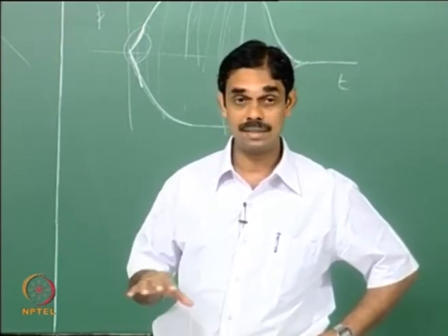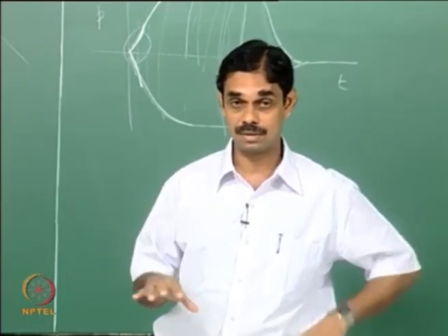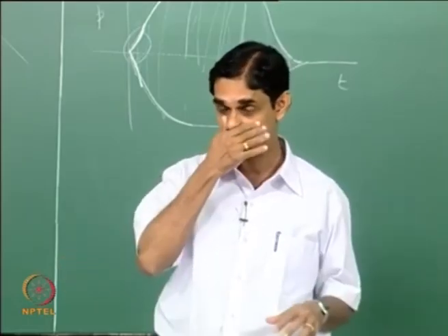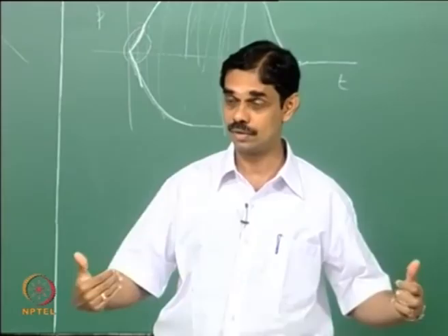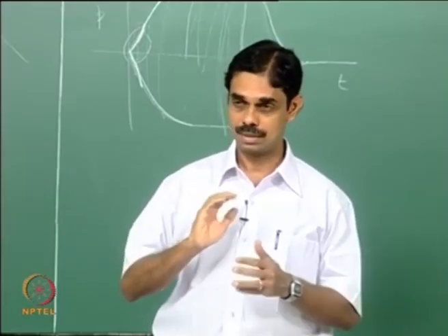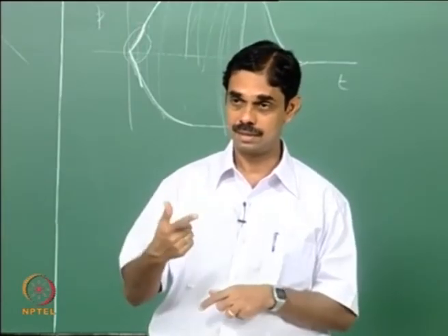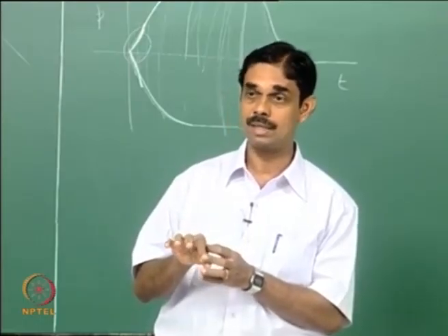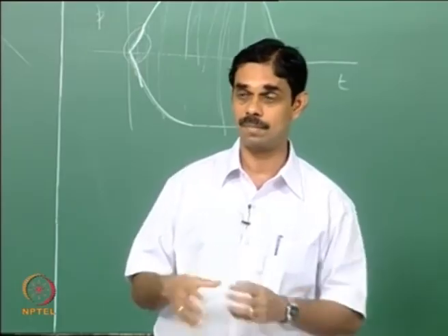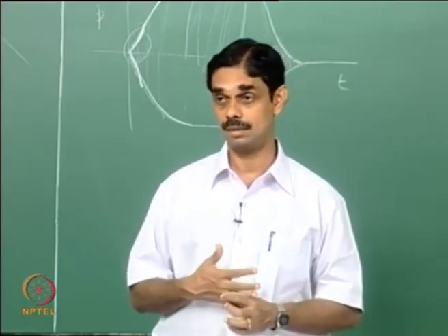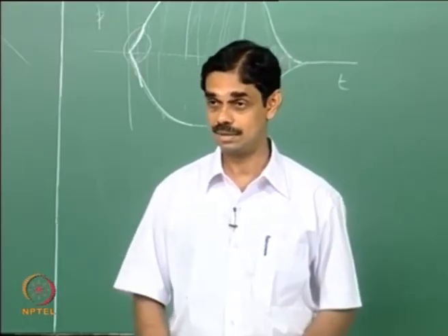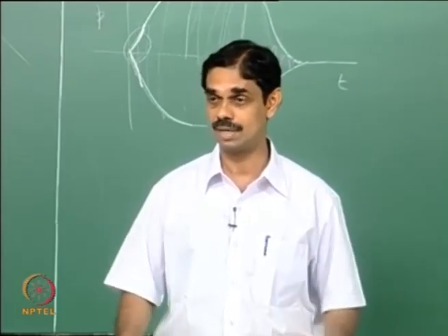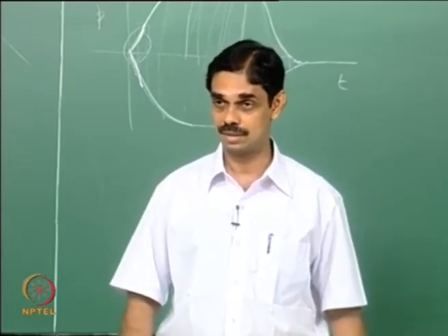Axial modes are very easy to get because these rockets are typically long, and lower frequencies are easy to come. The next dimension is the circumference. The radius dimension is very small, so naturally the frequency associated with the radial mode will be very large, and a propellant may not respond to that. But there is no blanket statement I would want to make, because every kind of thing has been seen somewhere or the other.